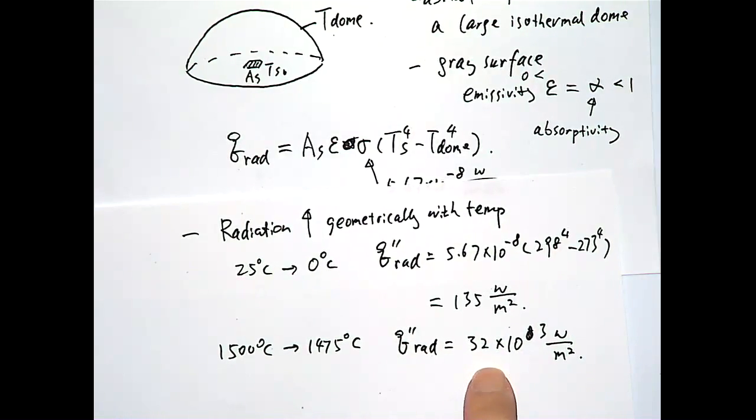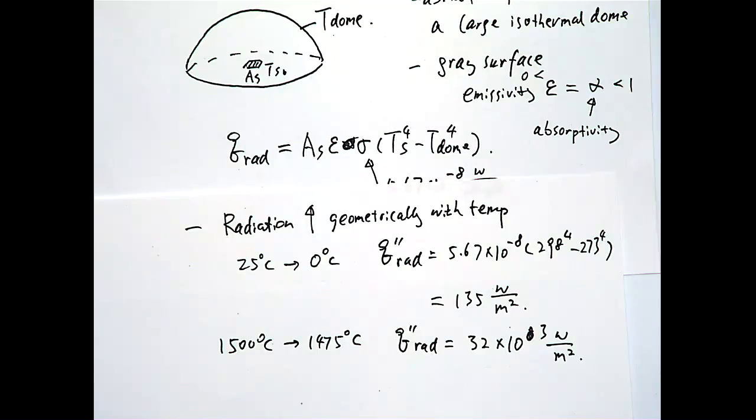So this value you can consider is about 20 to 30 times of the sun directly shining on the equator. And because many parts of the world are not on the equator, that solar radiation typically is around 1 kilowatt. So in summer, midday at Melbourne, that value is about 1 kilowatt per meter square. So you can consider that's quite a large number if the radiation happens at high temperature.